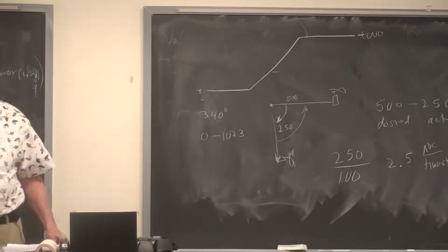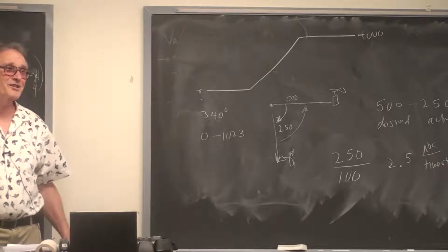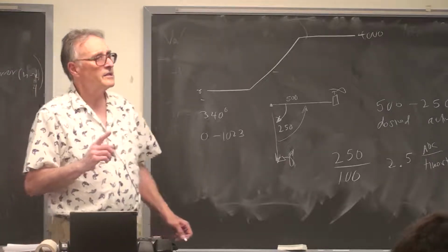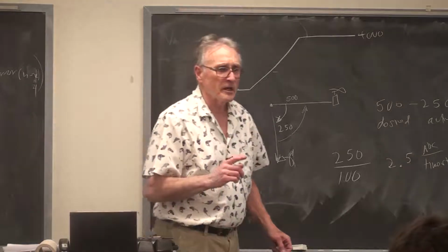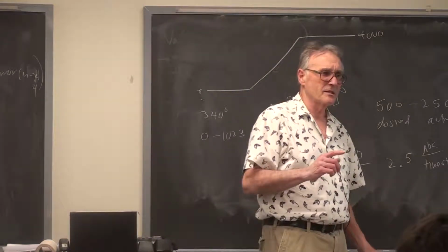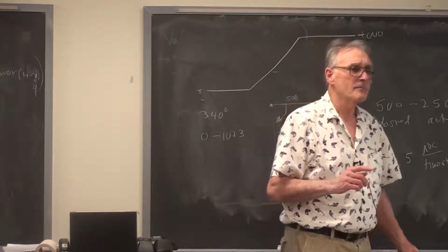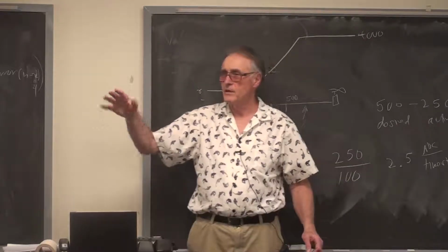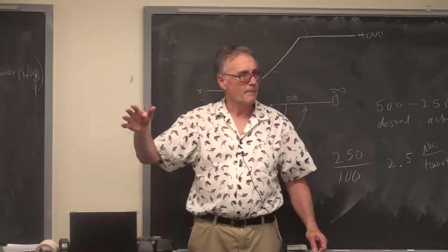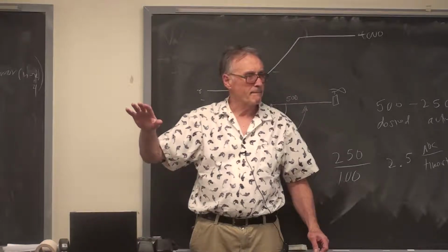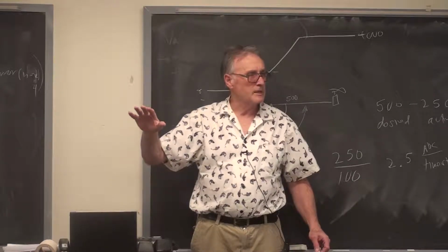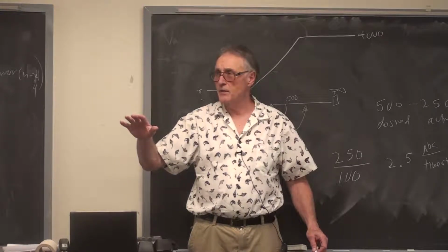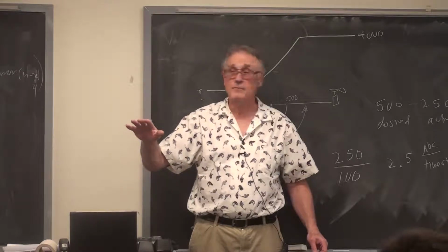By the way, these precision potentiometers are only precise in the sense that they are linear and have low friction. The absolute value of the resistance is pathetically off. Most of them I've seen measured have been around 8.7 kiloohms. Luckily, except for measuring the 50% point of the potentiometer, you don't actually need that number.